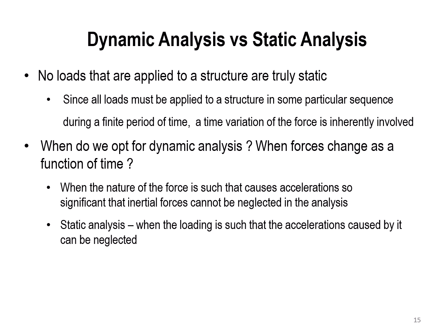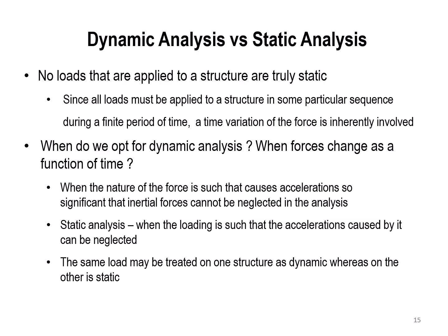Static analysis applies when the loading is such that the acceleration caused by it can be neglected. The same load may be treated as dynamic on one structure, whereas on another it can be treated as static.